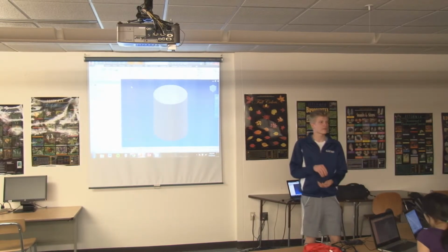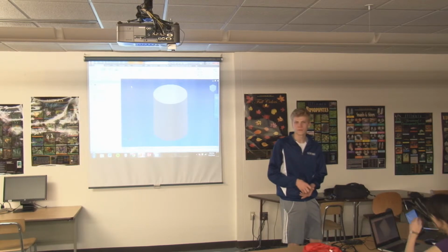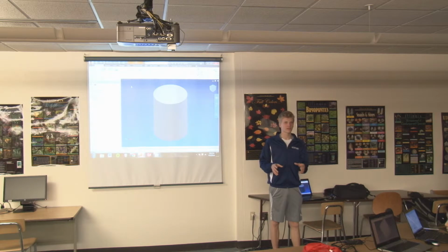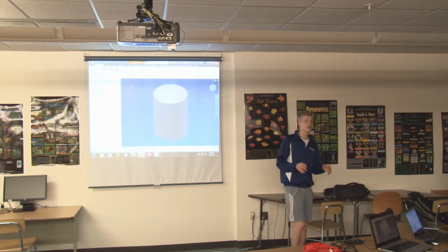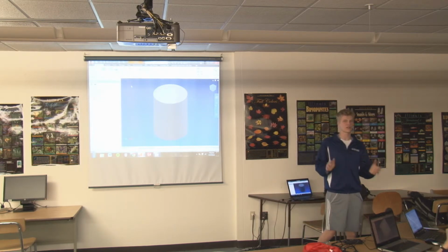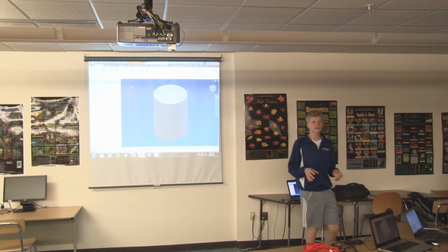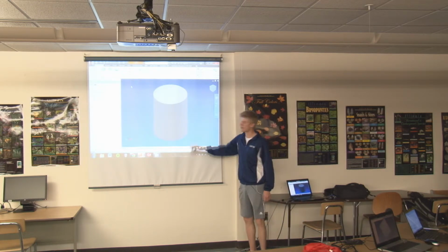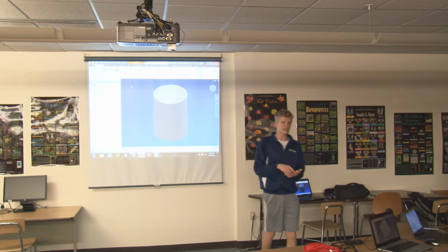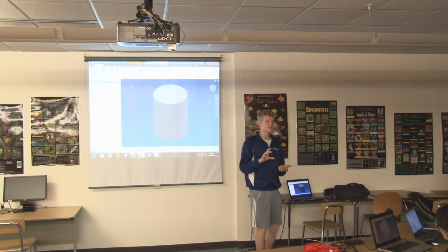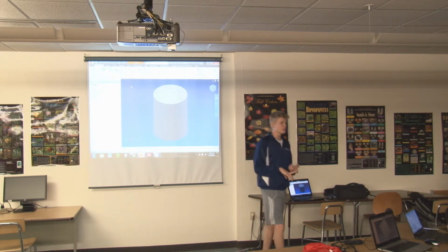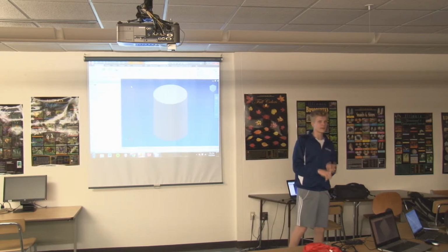So now this is a part file. This is one part that you have. Obviously, when you create your models, you don't want to do it all in one part. People go crazy and try to do everything in one part, and that gets really annoying because you can't change individual features and it gets overly complex. When you create models, you make a number of smaller three-dimensional parts like this. They're normally simple things, unibody pieces. For example, when CADing the robot, a nut would be one part, a bolt would be one part, a single piece of aluminum would be one part.